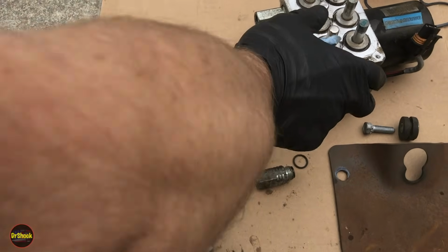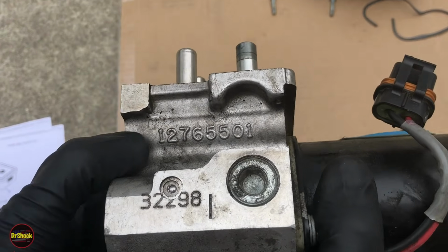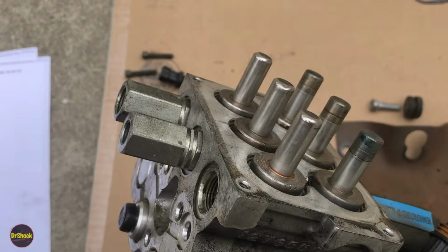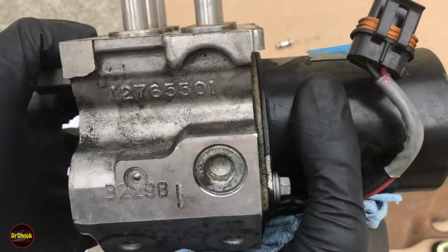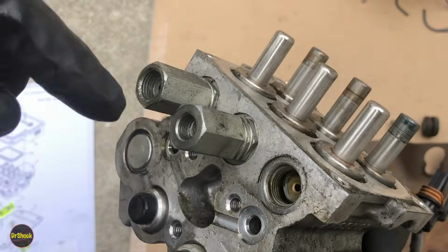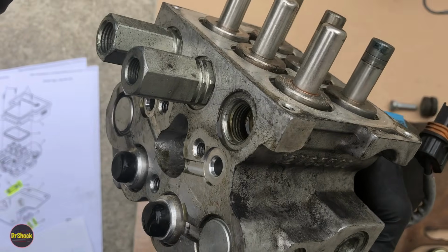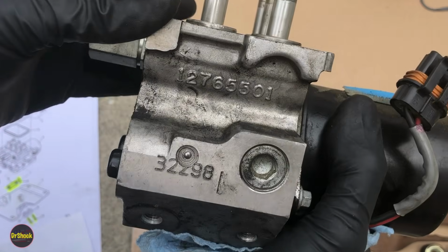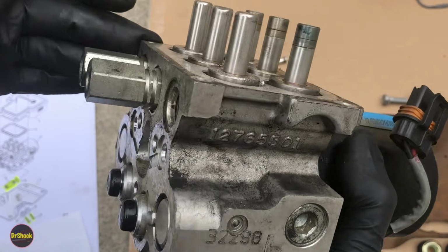When it comes to the BPMV, all of them are going to have the same casting number, 127-65501, but they're not all the same. The one for the S&T trucks is unique. Only the S&T trucks have the particular type of solenoids and internal jetting and plumbing that truck has. They're not used on the G, the P, the C, or the K, but they still use the same casting. So you can't use the casting alone to identify a BPMV.